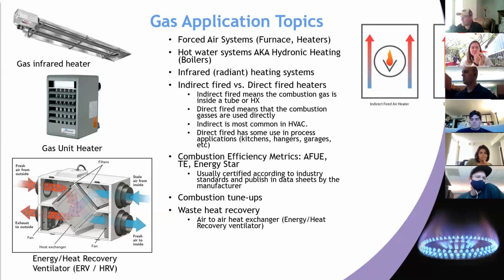When you start getting to something higher than that, like 8 or 12% oxygen in your flue gas coming out, that means that you're sending in too much air, and the nitrogen that's going in with that air is carrying away some of the heat that you could otherwise use. So that's why the objective with our flue gas analyzer is to identify how much excess oxygen there is, and then recommend that they bring it back down to a lower or a more efficient operating point.